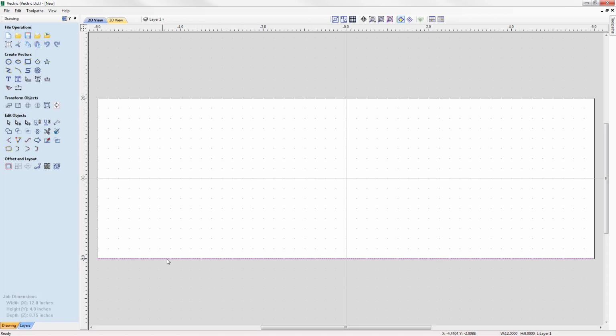Okay, now I'm going to create a copy of this line exactly 1/2 inch up the y-axis. So to do that, I'm going to select it. Then I'm going to hold down Control. That will enable me to create a copy when I come to move this line. And then using my left mouse key, I can move it. So you can see this is the line that I'm going to be creating. And as I said, I want to move it 1/2 inch above. Okay, so we know each one of these dots represents 1/4. So here it is at 1/4. So I'm going to snap to the 1/2 inch. And there we have it. So there's our newly created line. There is our existing line.